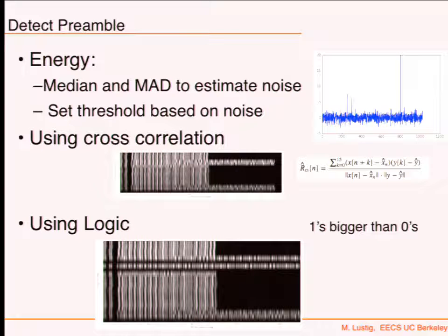You're going to do that, and then extract packets, save them in a matrix, and display those energies as images. And you see that they're aligned nicely. Each row here is a packet. You see the packets align nicely, and you see 2 long squirts and many, many short squirts. And you can see the preamble.